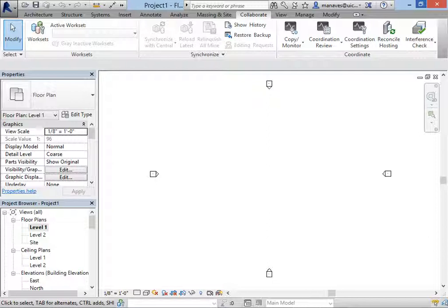There are no layers per se in Revit. We use work sets to define our model. And then we might make specific work sets that define certain parts of the building. So say Jim wants to work on a certain part of a wing, and I want to work on a certain part. We're working from one file, but people sort of check out components or parts of the project. And you can see who has what.